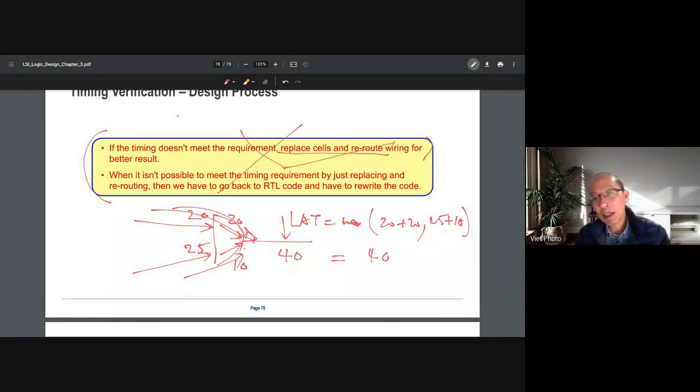And when you want to shield it, it's not easy because it's compact, it's dense. It's routed already, and when we see this signal is critical and you want to shield it, it will impact the other routes and cause more trouble. So the better way is just to reroute it, go a different way, so that you don't have the noise anymore.